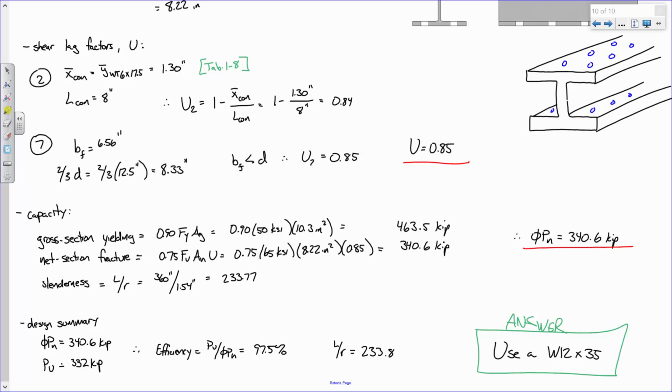You would be surprised at how much stress you can generate through thermal expansion and contraction. It's nuts. If you were to restrain this and let it go through a typical temperature cycle on a given day, the amount of stress that you would generate is insane. That abutment would just be gone. You have to let the bridge move. It's got to move.